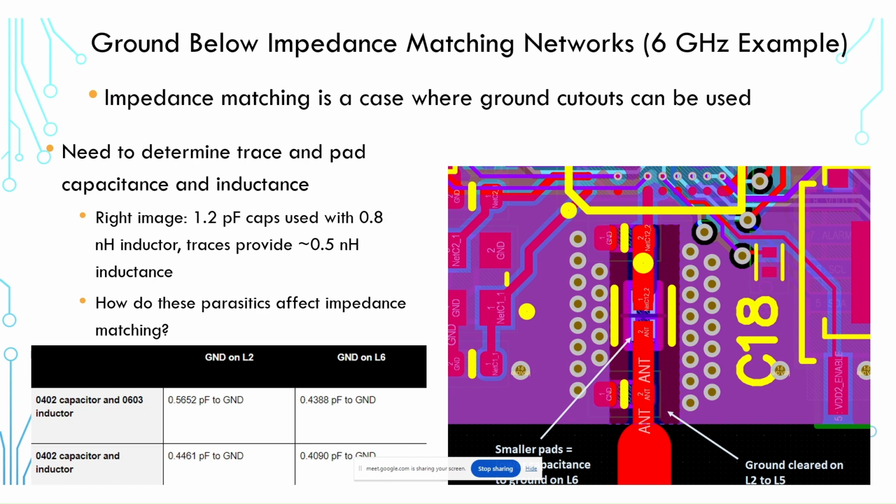Also, Robert Feranec has a really good video where he runs over how to do this on a spectrum analyzer with a prototype, and then you can observe very clearly when you get optimal impedance matching across this interface. So, Eric, maybe I'll share that video with you once we finish up, and you can share it with folks on LinkedIn.